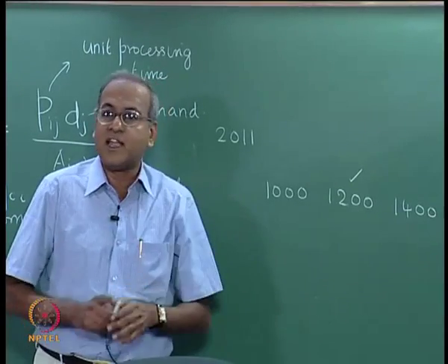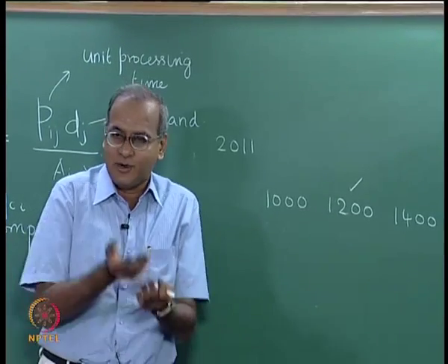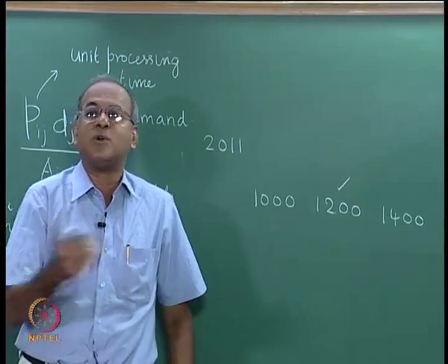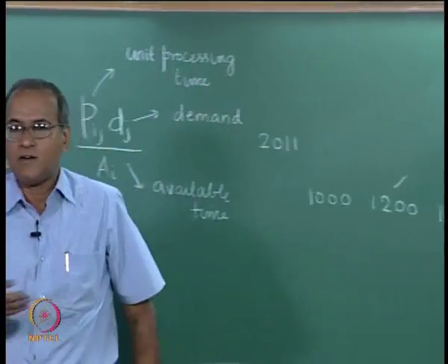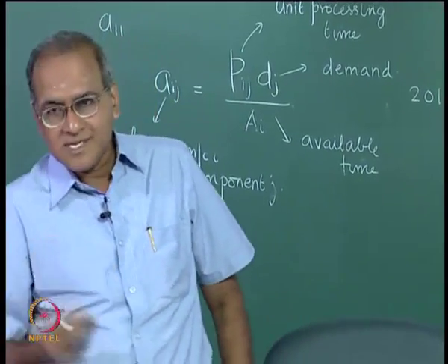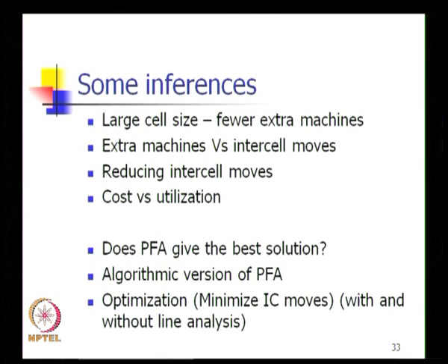So right at the beginning we would have added one more machine when it was not required at all. When the utilizations were about 80%, we would have 2 machines which would give us 200%, and we would not have wanted to spend that kind of extra money on the cell. So this kind of a trade off between cost versus utilization will be there right through.